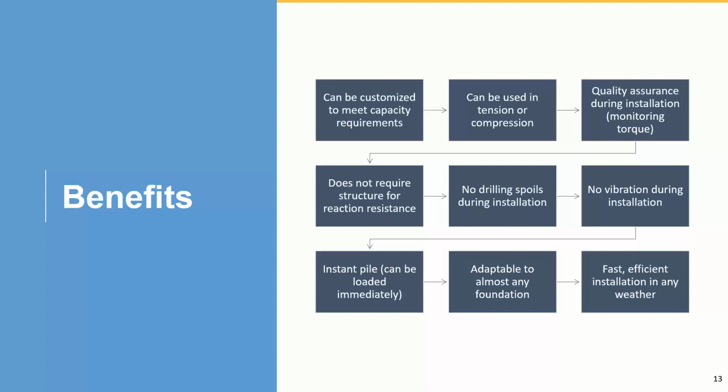Also for helical piles, if you really need a larger capacity, because like I said, these shafts have rated capacities. For instance, the 4.5-inch pipe has a maximum capacity of like 140 kips ultimate. But if somebody wants to use a 4.5-inch outside diameter shaft with an ultimate load of 200 or 250, you can grout that shaft and increase the axial capacity, and grouting can also increase the lateral capacity of the helical pile.